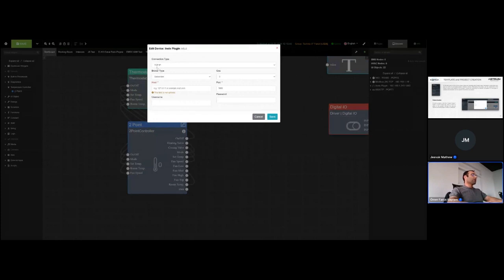TCP IP, you must select publisher, subscriber, both are possible to use. Here, we need to write our MQTT server IP address. Because there is no MQTT server on the Inspinia side, so you need a MQTT server.